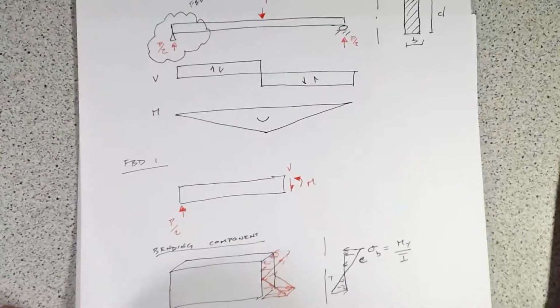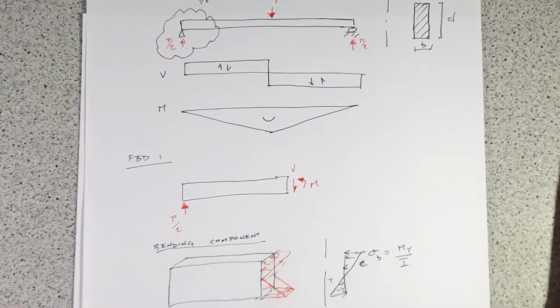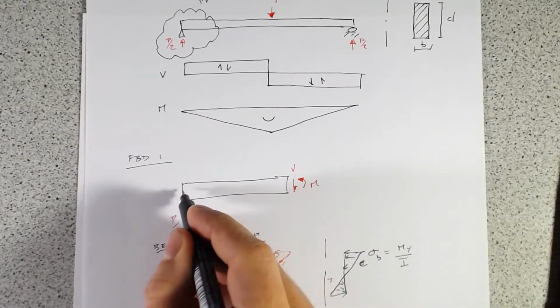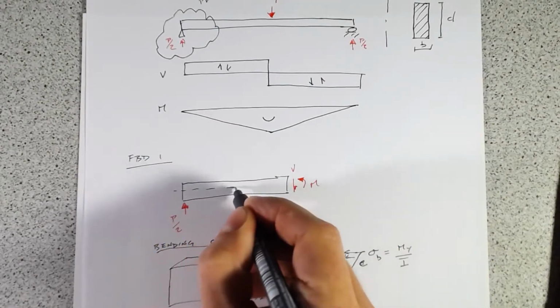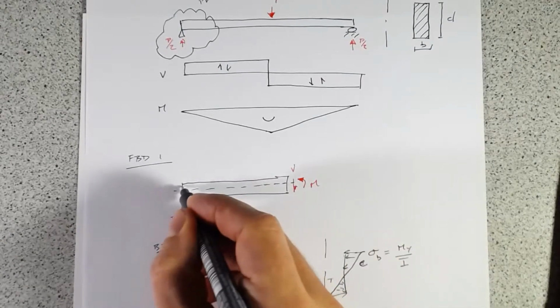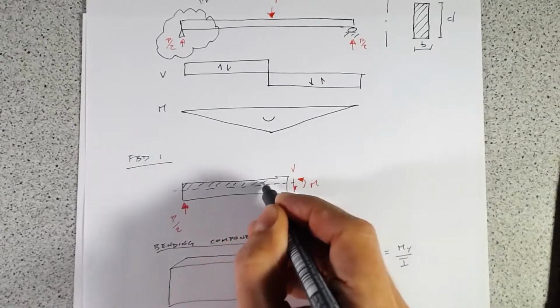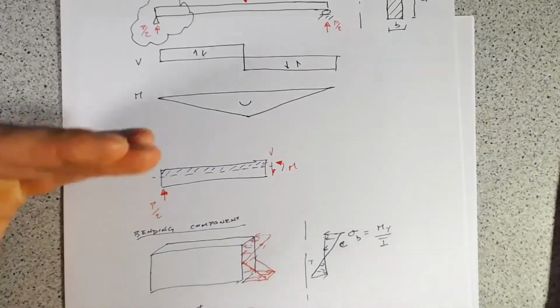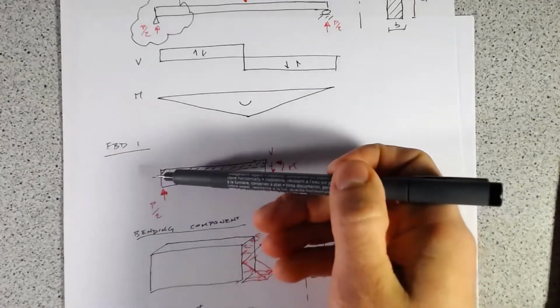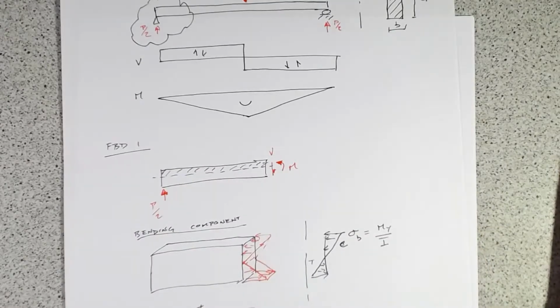So we will start with, again, the same free body diagram, but all we're going to do is take a second cut. We'll basically cut it through the top, and we'll look at this top section here. And we'll do that over different heights coming down, and we can see what the shear force is that's going to occur there. So let's start with that.